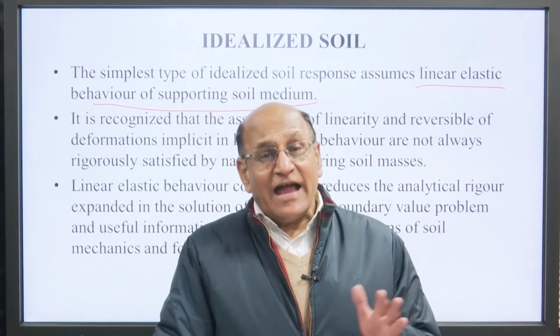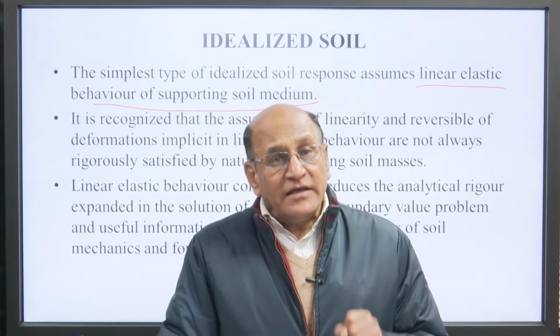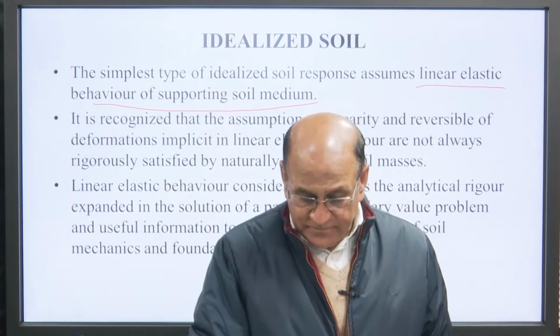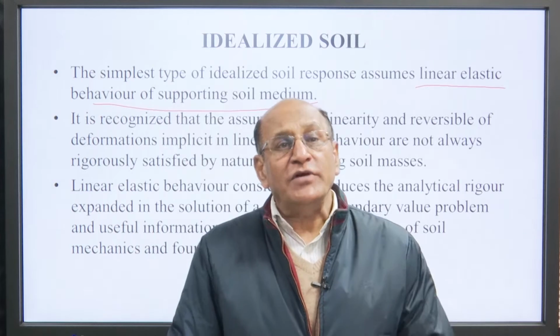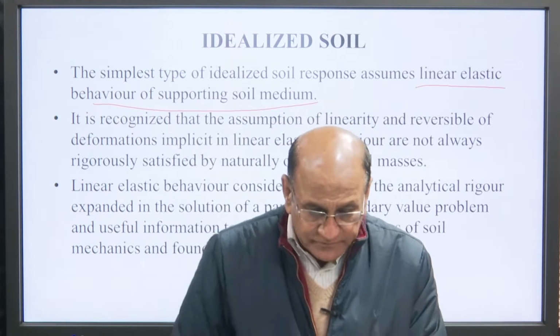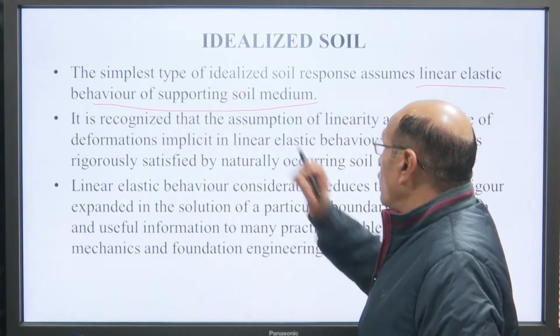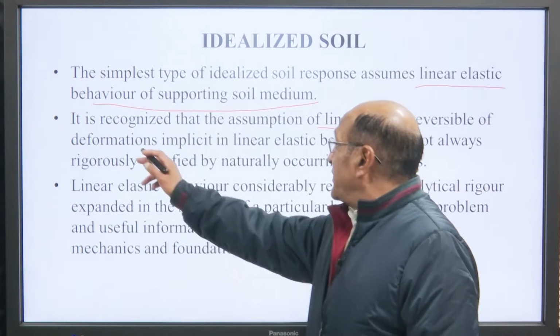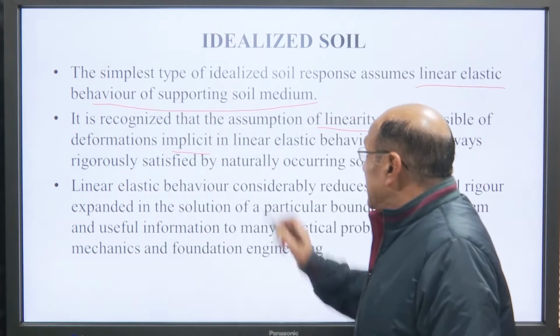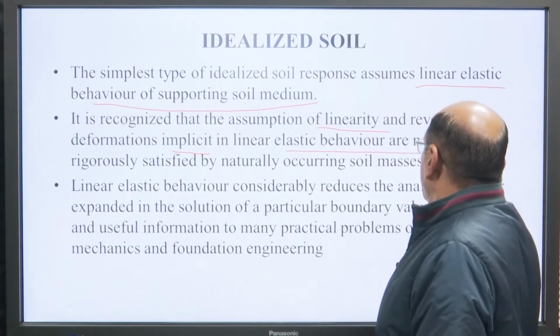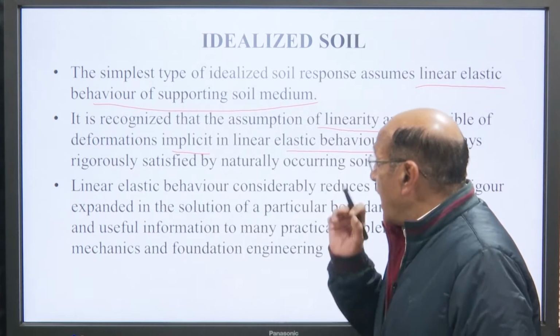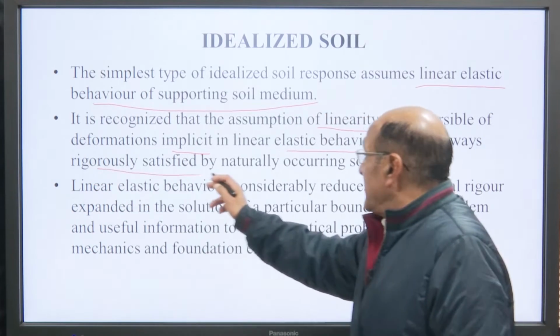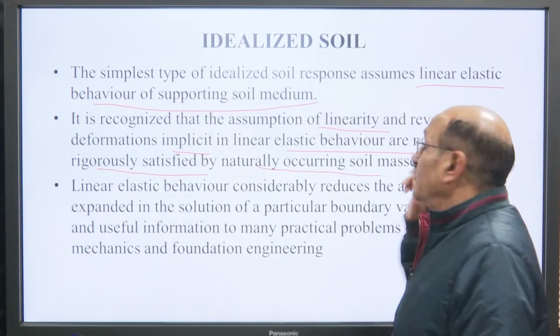This is important. It means the stress strain curve is constant, that is, stress is proportional to strain. It is recognized that the assumption of linearity and reversibility of deformation implicit in linear elastic behavior are not always rigorously satisfied by naturally occurring soil mass.